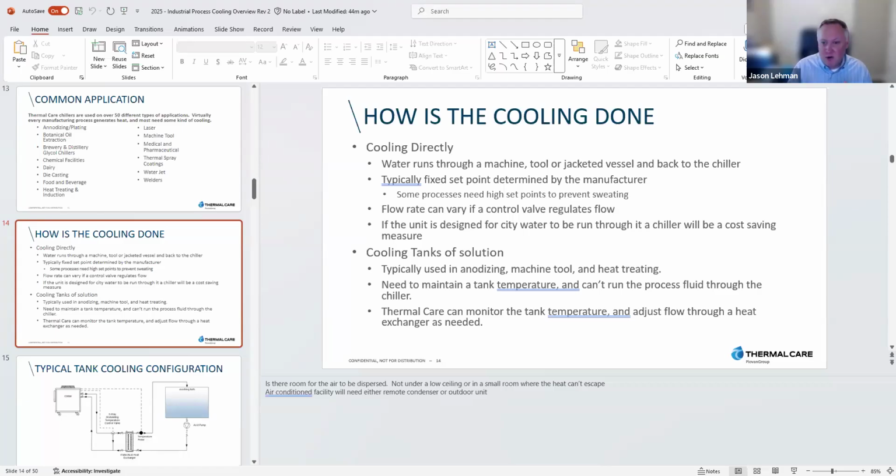Even if they don't charge, or they charge a flat fee, a lot of times they'll come in and basically flag something that is running city water down the drain. So there's hose connections on it. It needs cooling, and generally speaking, it needs a smaller chiller, like a package chiller. You can just drop it in right next to it, wheel it in right next to it, and run.